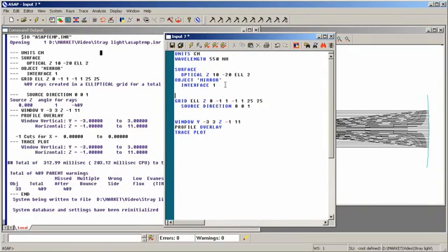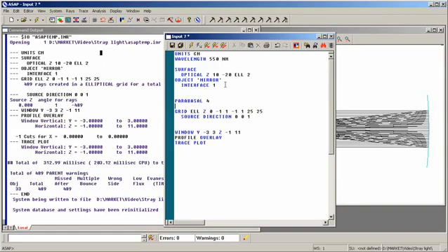We now want to turn this into a wave optics calculation. We do this by telling ASAP that we want to include not only the base rays, which represent the geometrical information, but also the parabasal rays, which give us the wave optics information associated with the Gaussian beamlets. We say parabasal 4, which says give me 2 rays in the plane of incidence and 2 rays out of the plane of incidence. Width 1.6 represents the Gaussian overlap from one Gaussian to the other. All right, we're ready to go.